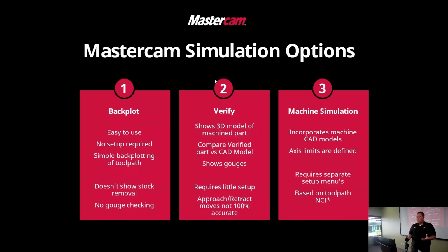So just to recap, the standard simulation options you're going to be familiar with within Mastercam are your backplot, your verify, and your machine simulation. Your backplot is going to give you a simple view of backplotting the actual code itself. There's no real setup involved with it. It's just going to show it right there on your screen. It's not going to show you any stock, and it's also not going to do any gouge checking.